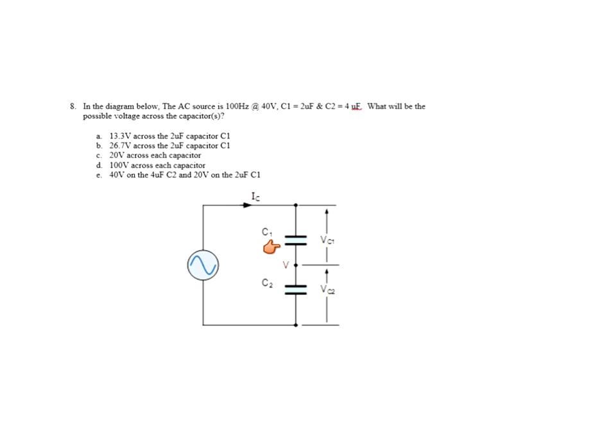C1 is the smallest. Now, what did we say about the smallest capacitor? It has to have the larger voltage. Don't worry about doing math here. You can do math and find it, but it'll take you too long. Look for the answer that tells you the smallest cap has the larger voltage.